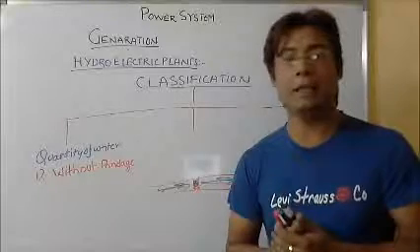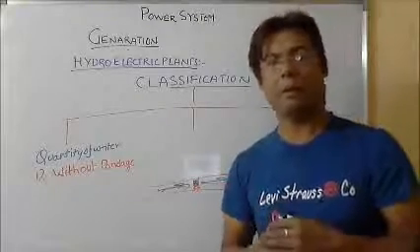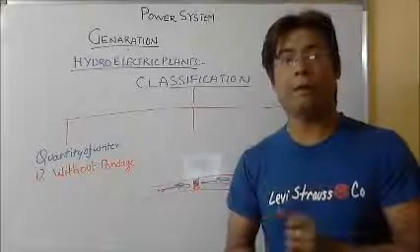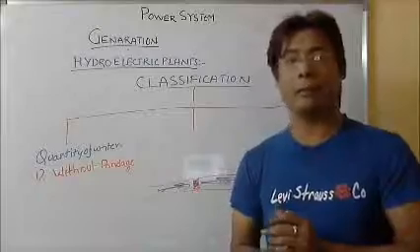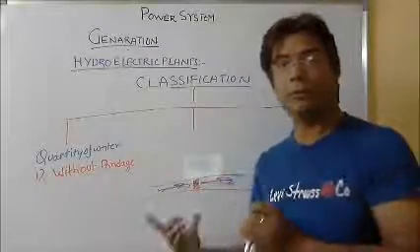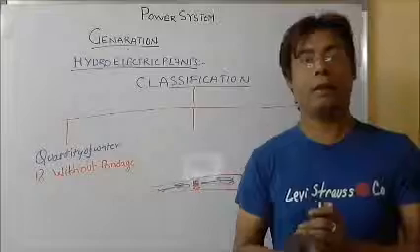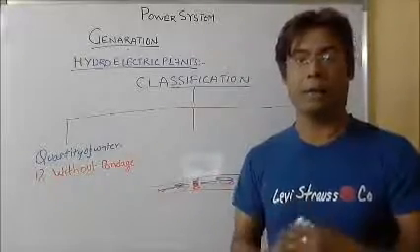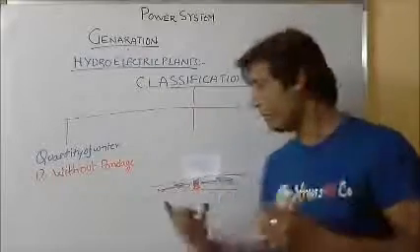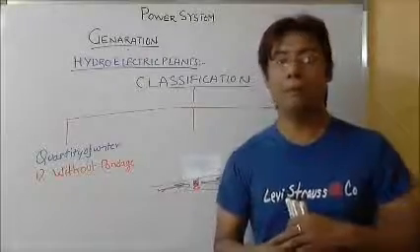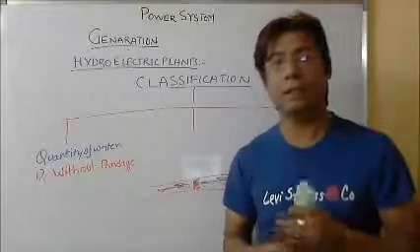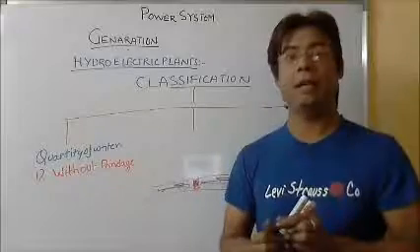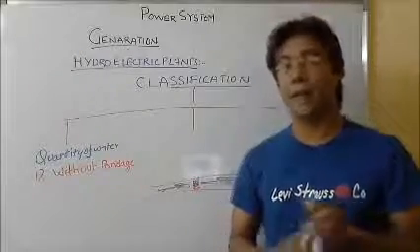But in March, April, May, it will not have the capability of delivering that much of the power which is required. So these plants are used as the water comes, and when the water availability is not there, they are not used. So these plants have a very low efficiency in the sense of time. They are not as reliable as a normal hydroelectric plant with pondage.